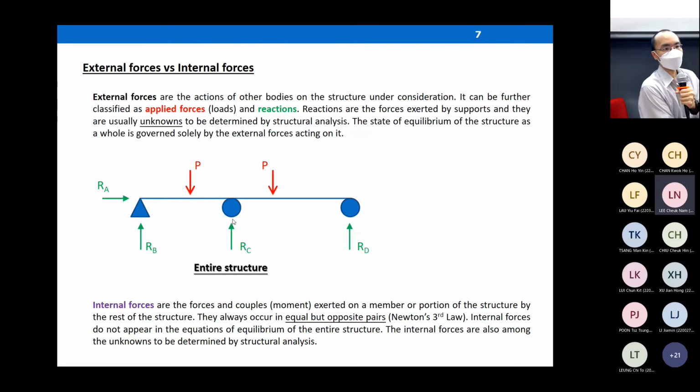The other thing that you have learned is the so-called external force and internal force. I just copied the definition from the textbook. I put it here because I found that students normally confuse external force and internal force. External force means something applied on the structure that you can see directly from the picture, just like here. Applied forces and reactions apply on the structure directly. So they are so-called external forces.